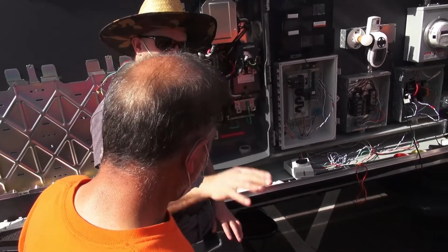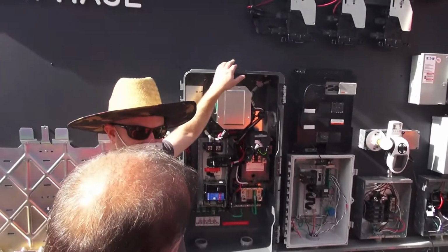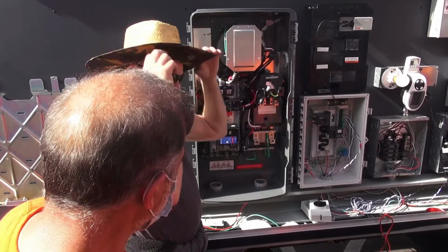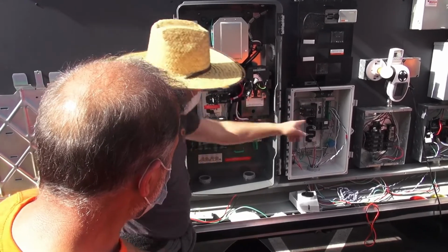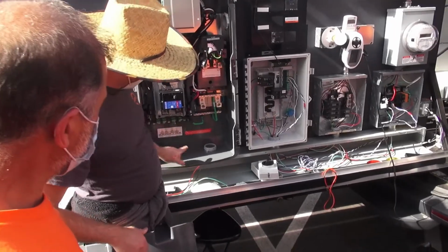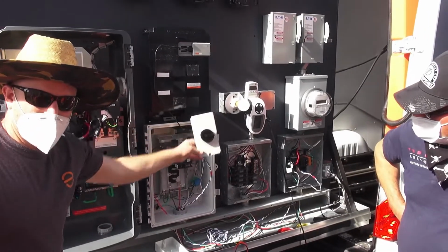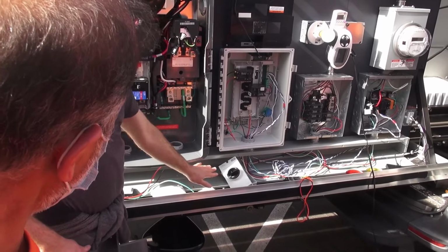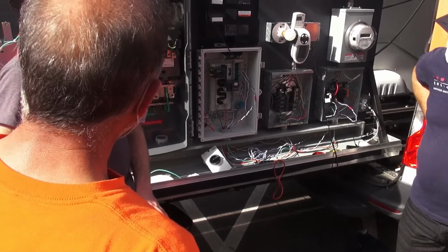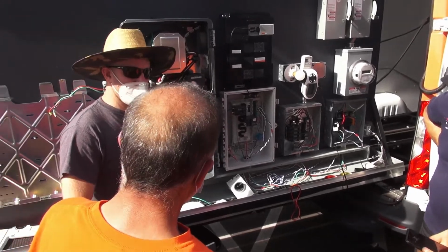So this is an important thing for you. This is confusing. Everybody here, you're like my champions right now. There's different versions of equipment. Once you start installing this version 2, you're gonna kind of change your hat and say, that one I gotta do this, like these flip. Some minor important things. If it's a System Controller 2, I'm gonna install a rapid shutdown switch over here. System Controller 1 does not have this switch. So these are important. If I'm giving you a little bit of a brain moment here thinking about it, it means you're gonna have to recognize which one's which, okay?